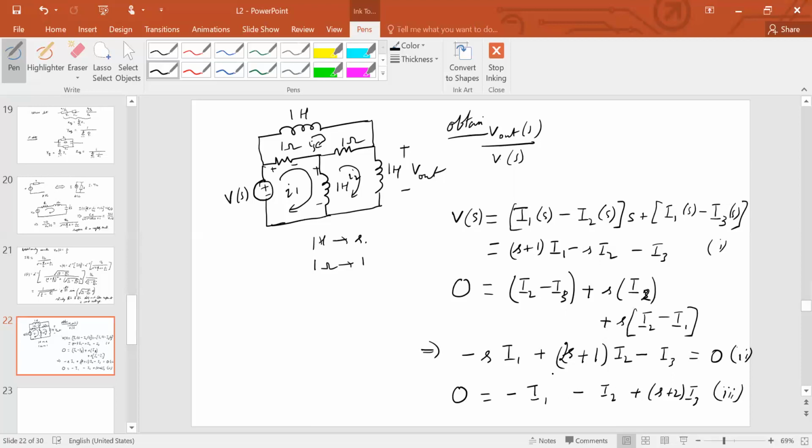So now you don't even need to bother about writing these in a careful fashion in two lines. Anytime you encounter a circuit like this, on the left hand side, just write the externally applied voltage or current source, voltage source in this case. And on the right hand side, you can just apply this technique. For the loop variable for that particular loop, it is the sum of the impedances across the loop. And for the cross terms, it is just the impedance that is common to, that is overlapping between the given loop and the loop with which the other current is associated.